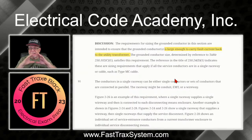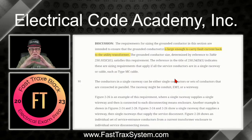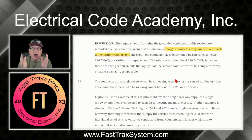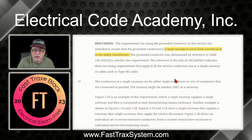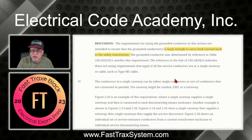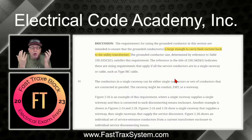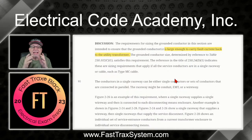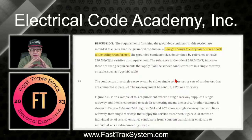Like you might have an EMT with two sets. Maybe you're running two sets of 4/0s or two sets of 350s. And maybe your raceway is large enough and you're not exceeding the 40% raceway fill that's covered in Chapter 9, Table 1. So maybe we're okay. And that's all in one raceway. Okay, so that's what it's saying. We're simply talking about one raceway.